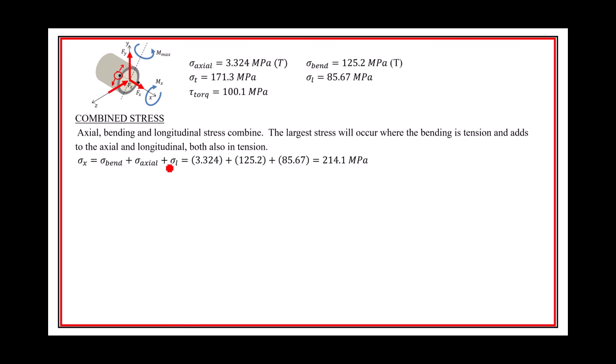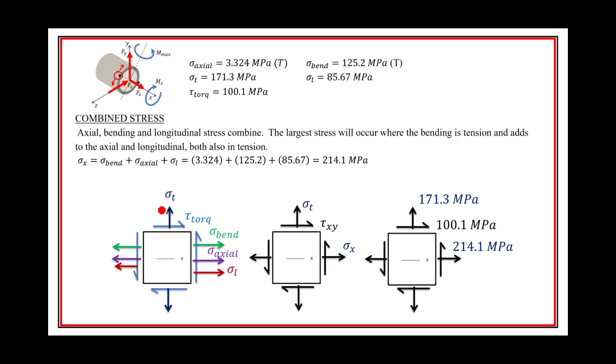So I add those together to get the total stress in the x direction. And I show that down here. And you also note that I didn't put a vertical coordinate. I just put a coordinate in the x direction, because the vertical part of this little element that we see isn't really aligned with either the y or the z. It's somewhere in between. But here, getting a stress element and getting all three main stresses onto it is summarized right there.